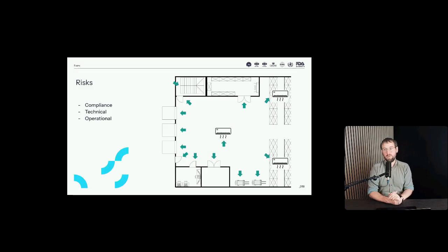We've done it with customers before, and it has been accepted by regulatory bodies and auditors. When doing smaller segments at a time, you should be cautious about how you define the hot and cold spots, though, because when you do place sensors in the entirety of the volume at the same time, you will have measurements that are very comparable. So the measurements will be comparable to each other. Whilst when you do it in smaller segments, there is the chance that due to external variations, due to differences in how you do your door opening and power failure studies, or loading and unloading, that could have an influence.